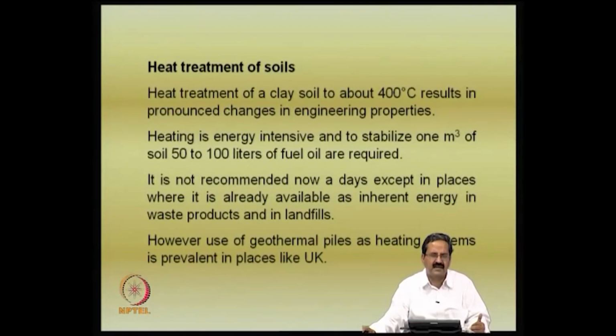In fact, I was testing soil from the Cochin area, which is very soft. You can keep the soil in the atmosphere for some time and find out its liquid limit in the natural state. The moment you bring the natural soil, put it in plastic covers and tie it, then bring it to the lab and find out its liquid limit, you will get some water content. But then you take the same amount of soil and keep it for air drying, which essentially means you are subjecting it to ambient temperatures, whatever exists here, either in Bangalore or Kerala.